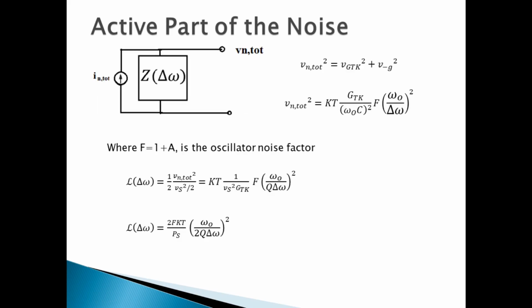So phase noise is basically the reciprocal of the carrier to noise ratio. It says something about how much energy I have at the carrier exactly and how much energy I have close to the carrier. And ideally this carrier to noise ratio we would like to have as large as possible. I'm talking about carrier to noise ratio, not noise to carrier.